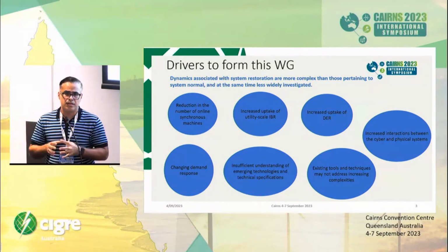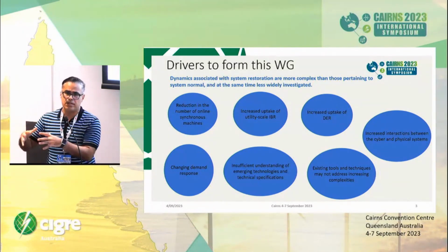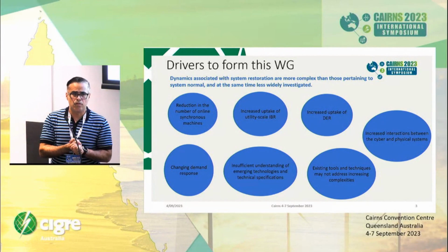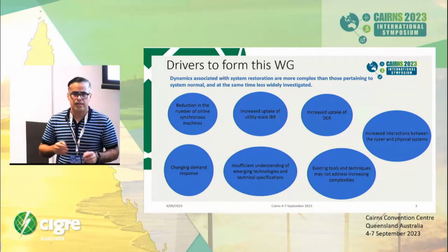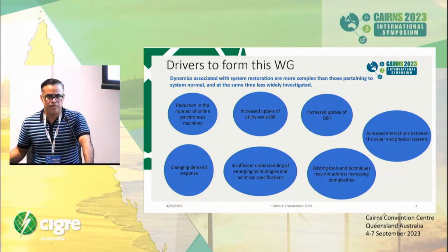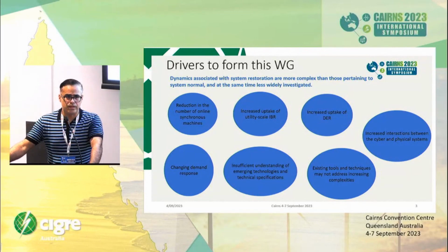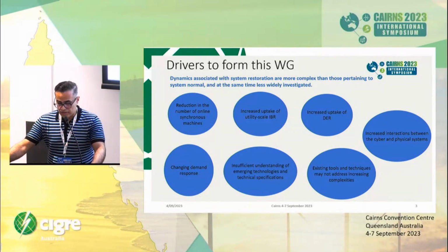With system restoration, on one hand is the generation, but that generation relies on being fed by loads. The assumption to date has been that sufficient passive load, like heating load, is available to be picked up. But if it is not available, how could that potentially impact system dynamics during restoration?